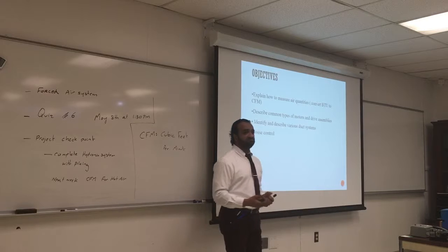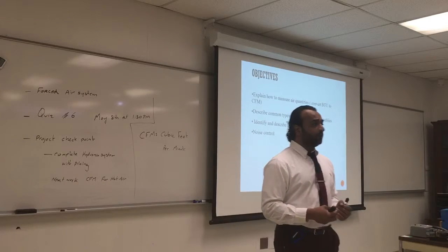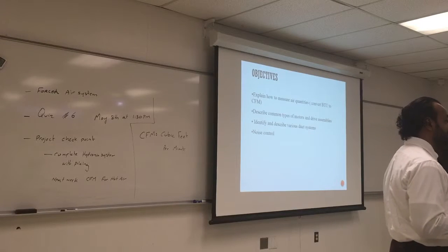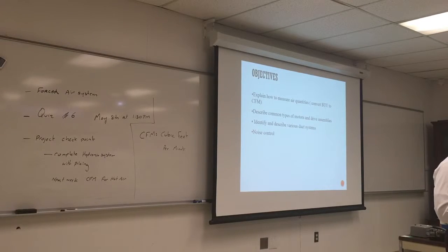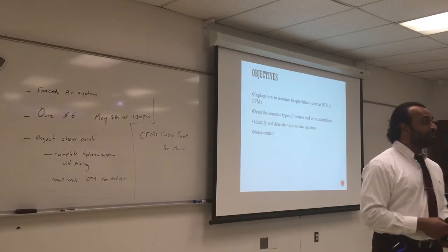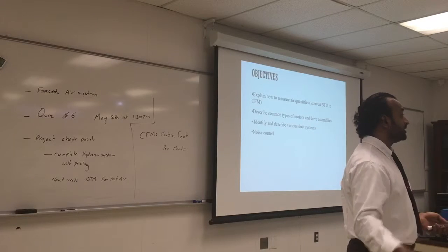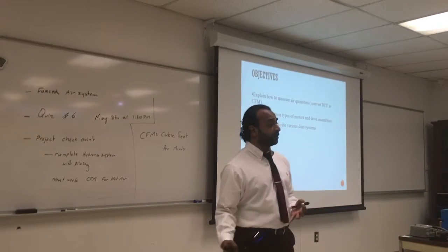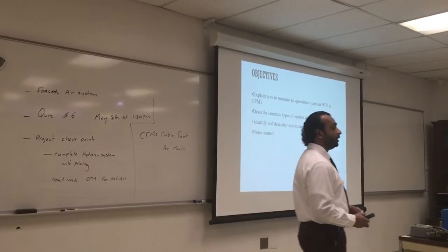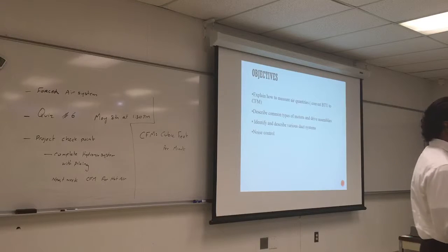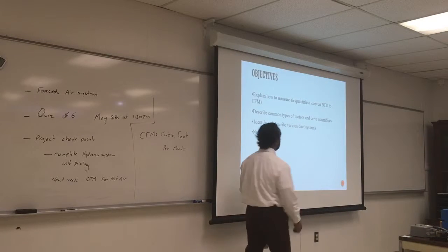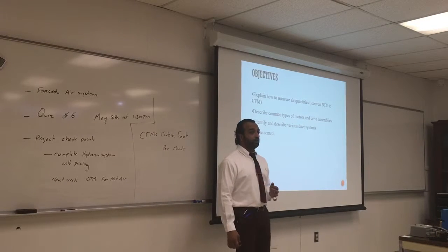Various duct systems. What kind of ducts do we have? We have either return and supply. Sometimes we have fixed duct. What do we have? Aluminum, GI, galvanized steel, galvanized aluminum. We also have flexible duct, which looks like hoses. We have high velocity duct. There are so many possibilities to deliver air to the room. They all have advantages and disadvantages, and they can all be suitable for one application but not the other. So we will talk about different aspects. And finally, noise control.